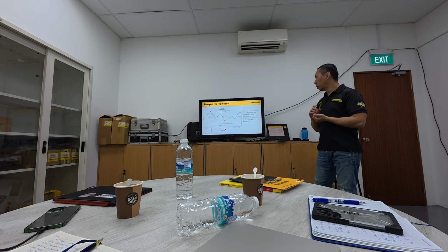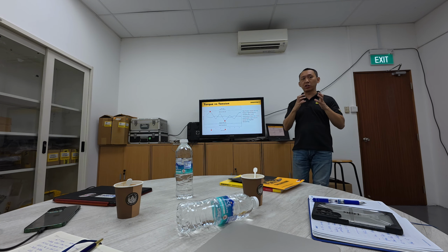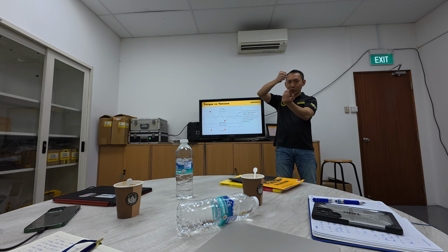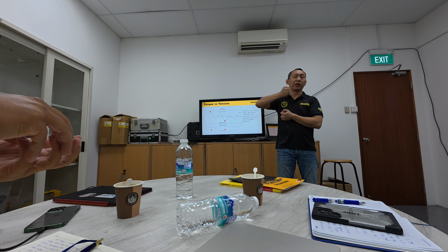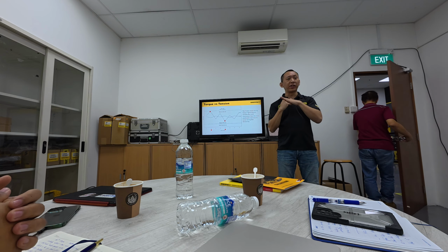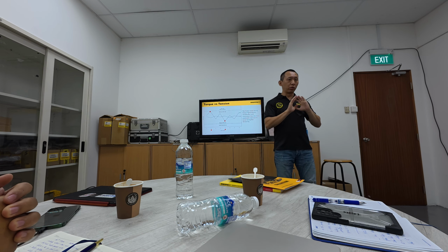So the frictional loss during bolt torquing I consider more inconsistent than the more visible loss during bolt tensioning. Because why? Because in bolt tensioning, what are you doing? You are pulling the bolt, the stud, using the adapter. You are pulling the stud, and there's no friction, because you are pulling. There's no friction loss, and no friction between the surfaces of the nut and the joint.